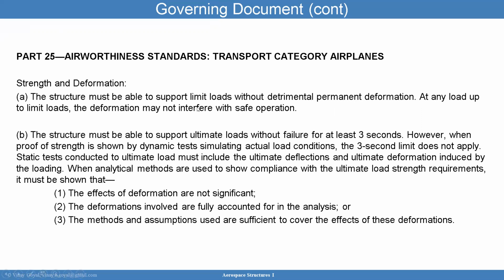In other words, at limit loads, the structure has to be functional. And then you have to show that at ultimate loads, there's no failure for at least 3 seconds, again consistent with the European standard. However, when the proof of strength is shown by dynamic testing to simulate actual load conditions, the 3 second limit does not apply.